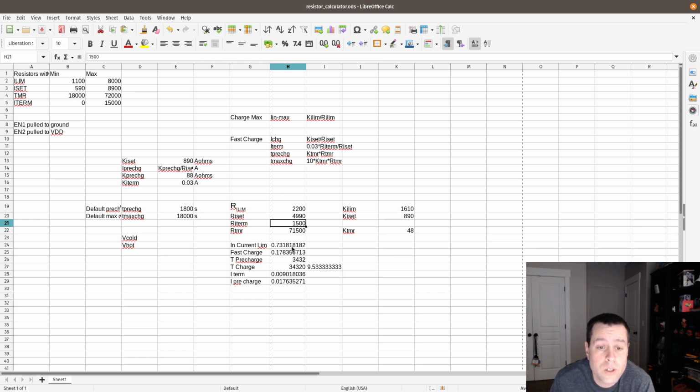So this is as much current as the PMIC will consume to both run the device as well as charge the battery. So this is sort of your total bucket of current that you have, regardless. Like if your charger can supply an amp or 2 amps, it doesn't matter because of how I've chosen these currently, it's only ever going to consume about 730.2 milliamps of current total. Again, to run all the electronics on this board, as well as charge the battery when it's plugged in.